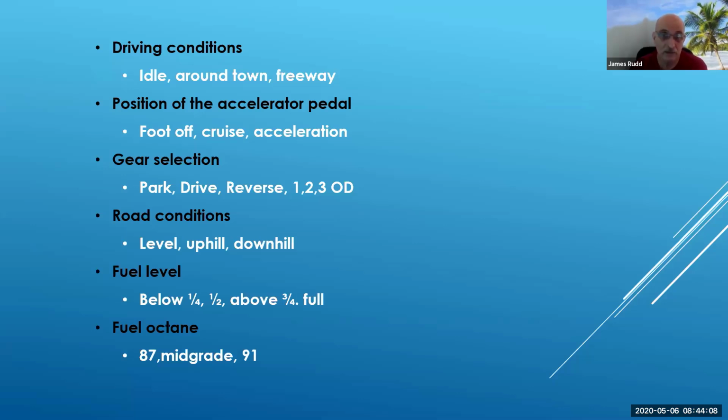If I have a hesitation off idle, I could have a bad part of the actual carbon resistor pad that has a drop off. And I would find that potentially by doing a sweep test on my TPS, or throttle position sensor, with a lab scope or a DSO to see that drop off happen.